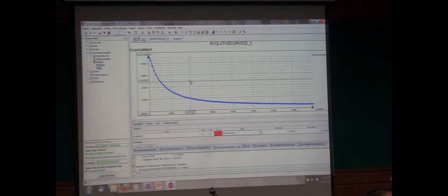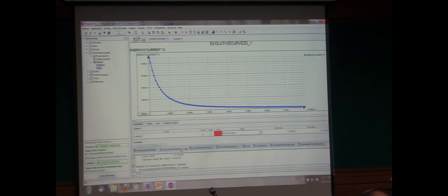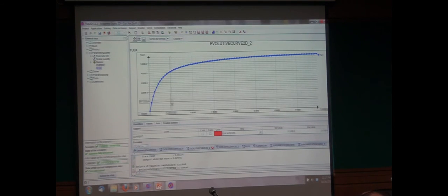I did say that the derivative was another way. So if I look, I did my curve, I think it's not this one, sorry. Here, this was my flux curve from before. Well, this curve, actually I can do a right mouse click, and by the way, look what I can do. I can edit, I can export it, in fact, in an Excel, but I have other things like integral and derivative. So if I derivate this, I have I in X, and I have phi in Y. So I'm going to get d phi di. And let's try to do this right here.